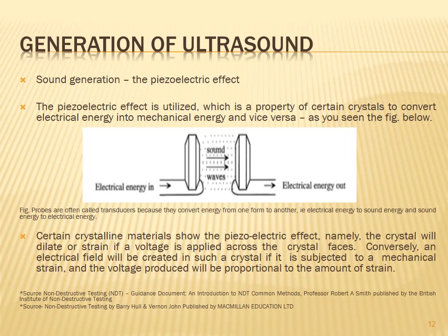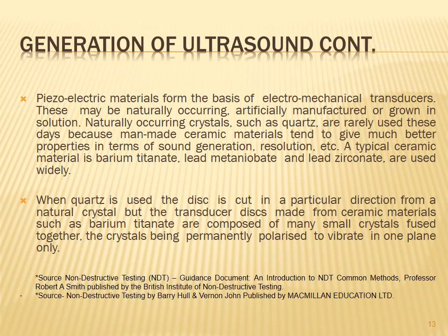Certain crystalline materials show the piezoelectric effect, namely the crystal will dilate or strain if a voltage is applied across the crystal's faces. Conversely, an electrical field will be created in such a crystal if it is subjected to a mechanical strain. The voltage produced will be proportional to the amount of strain. How is sound produced with the help of piezoelectric material? That is most important. There are different types of piezoelectric materials, crystals that may be naturally occurring, artificial, and manufactured and grown in solutions.